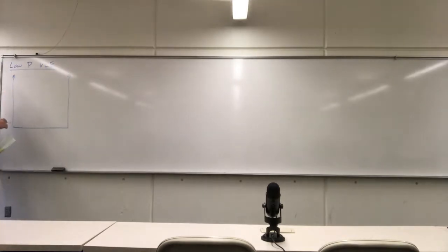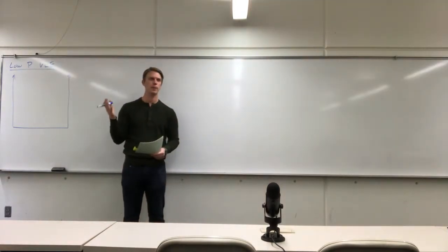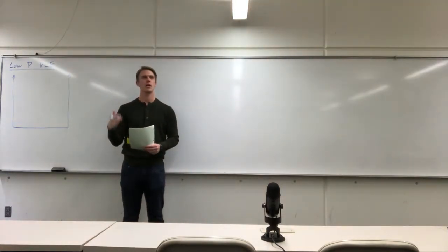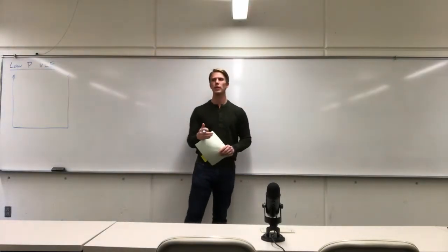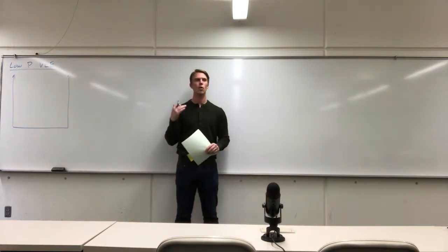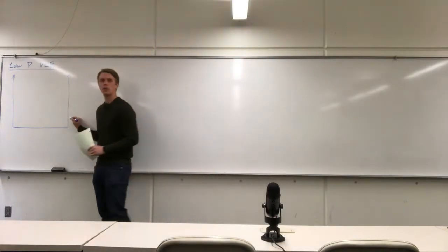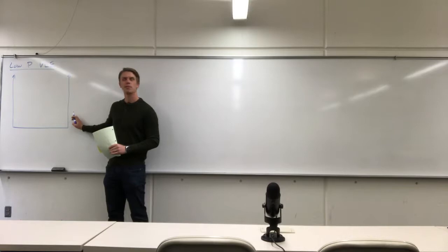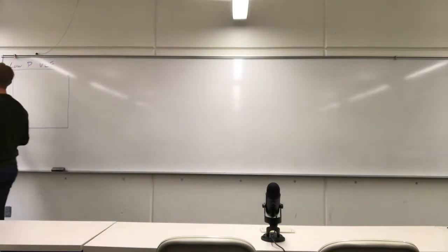So in low pressure vapor-liquid equilibrium, as we've sort of uncovered based on the questions for the homework, PXY diagrams are way easier to generate than TXY diagrams. The reason behind that is because for a Raoult's law system, PXY is an explicit expression. For TXY, temperature dependencies are always going to be nonlinear, right? And it's going to be a nonlinear equation that we can't rearrange to solve trivially. Now the reason why the TXY is nonlinear is just based on the Clapeyron equation. Vapor pressure is exponentially dependent on temperature. That's a bedrock fundamental conclusion of basic phase equilibrium.